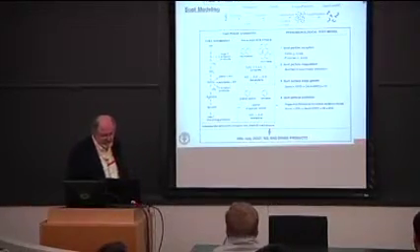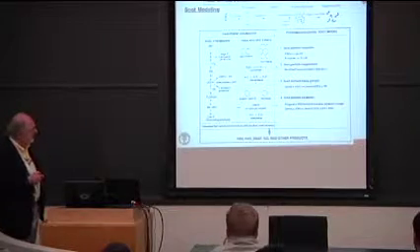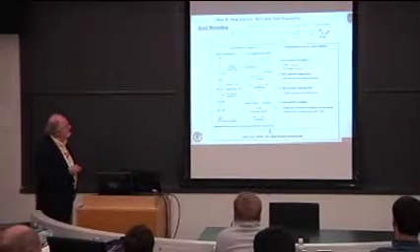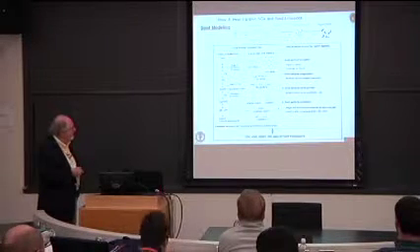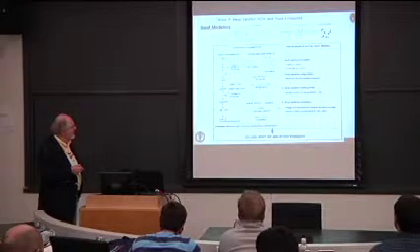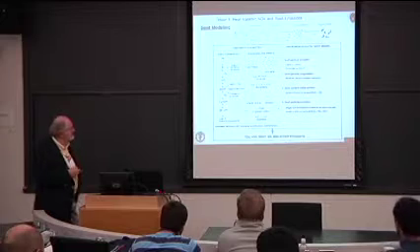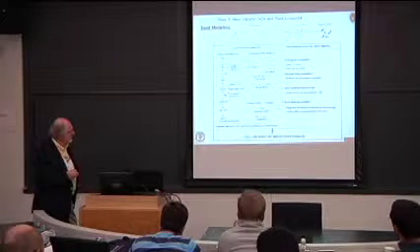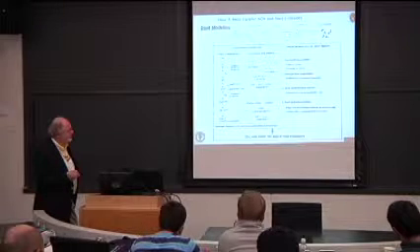So how do we deal with this? Well, if you go back and take a look at the data, this is from Dale Tree's paper, for instance, you essentially have these processes. You have the chemistry that leads to the formation of the soot precursor species. We've already discussed this chemistry when we spoke about combustion. Those soot precursor species include acetylene, C2H2, and propargyl.